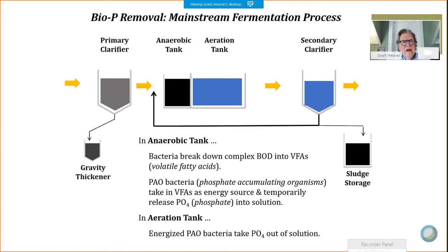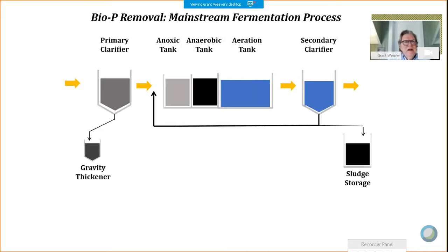Now, nitrogen interferes, right? So in the return sludge in this schematic here, any nitrates that are coming into that anaerobic tank are going to outcompete the phosphorus bacteria for whatever volatile fatty acids are produced. So I guess it's tricky. A very brilliant design concept is feed these less fussy eaters hamburgers instead of steak.